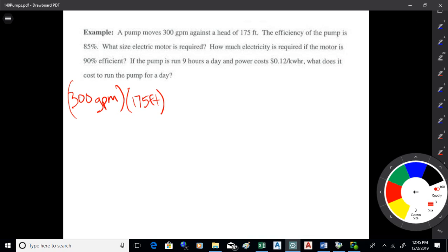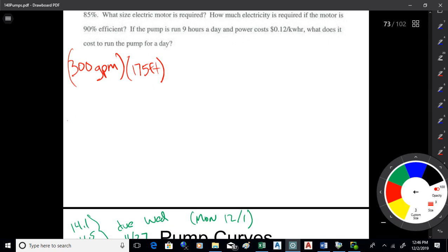So how much water horsepower would that be? 13, 14. Okay. So what's the last thing I have to do to get water horsepower out of that? Divide by 3960, that magic conversion. 3960, and that'll get me water horsepower. And that's 13.26.